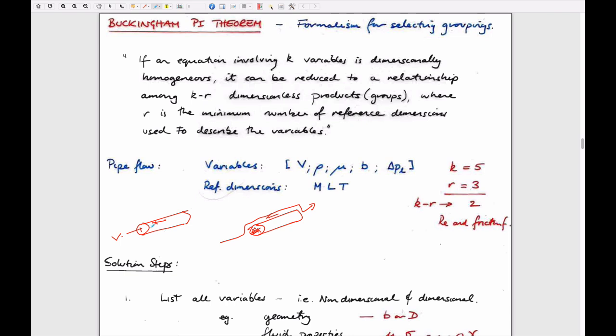And when we look at in-pipe flows, the whole essence of the problem is figuring out what this pressure loss is, because you want to dimension a pump for it. We don't care really about the fact that that pressure loss is manifest as a shear stress or a drag force, but it is, and we'd have to hold that pipe in place to stop it moving on us. Just as if we wanted to hold this tube in place, we'd have to apply a force to be able to hold it in place against the fluid that's going around it. The fact that the fluid's going around it and the shear stress is on the outside as opposed to the inside is immaterial. But they both would have these viscous losses.